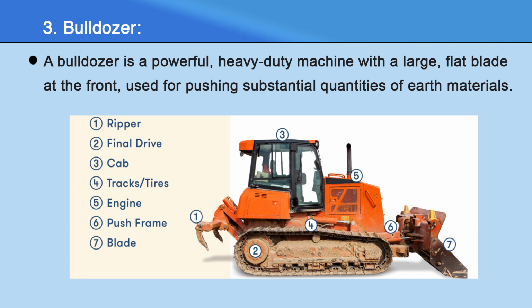The size of a bulldozer is determined by the length and height of its blade. Its capacity varies based on the size of the blade, the type of earth being moved, and the nature of the slope, uphill, level, or downhill. To determine the economic viability of using a bulldozer for a specific project, it is important to calculate the cost per cubic meter and select the appropriate type and size based on this assessment.